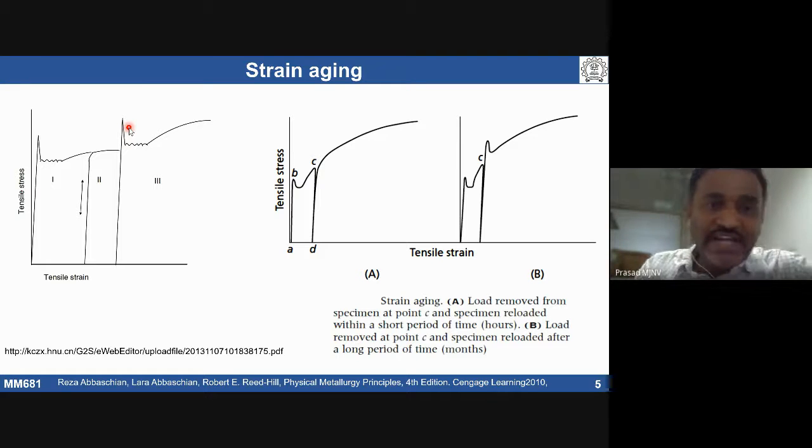We already saw this discussion in the previous lecture. For example, we take a fully annealed material, and we need only a very small amount of solute atoms to pin all the dislocations. Even if you take fully cold worked material, we only talk about 0.04%. I already showed two examples, fully annealed material and fully cold worked material. In both cases, the amount of solute atoms required is going to change in order.